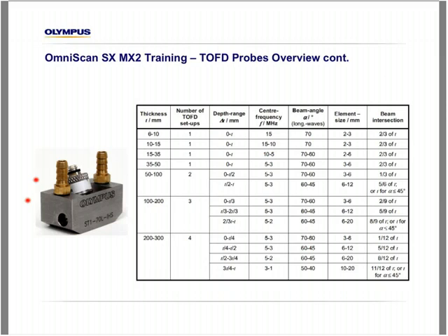The ASME codes mandatory appendix and EN codes all contain general recommendations for both the number of ToFD zones, the frequency of the probe, and the angle and element size. These provide some rough guidance for the best case scenario and at what thickness a second or third ToFD zone is recommended.